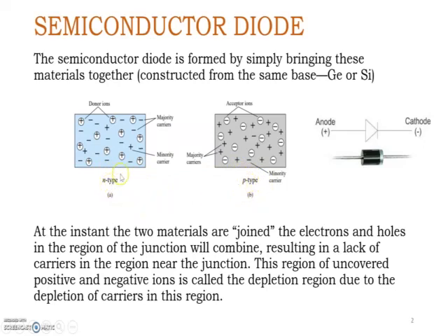In N-type semiconductor, the majority carriers are the electrons. You can observe that there are more minus symbols here, and the minority carriers are the holes. You can see only 1, 2, 3 holes are there, and the plus with the circle are called donor ions. Note that ions are not movable, right? Only the carriers, electrons and holes, will be moving. So in N-type semiconductor, majority carriers are the minus, that is the electrons. Minority carriers are the plus, that is the holes.